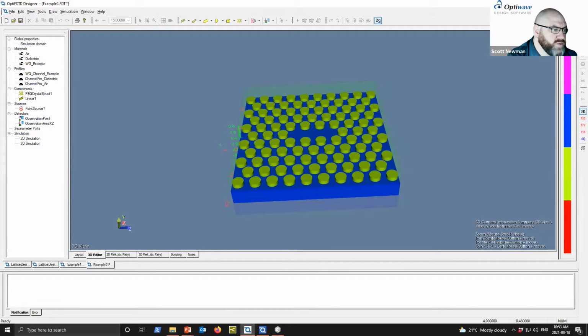Yeah, there's just one question here, again, in regards to the TE and TM. So when the video comes out, go back and look at the start of it. The OptiFDTD product reports, if you calculate a TE band gap, it will be a TM band gap in Molding the Flow of Light, if that's the reference you're looking at. If you calculate a TM, it matches the band gap in the TE in Molding the Flow of Light.